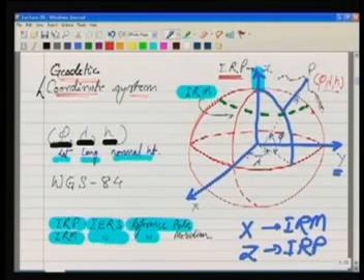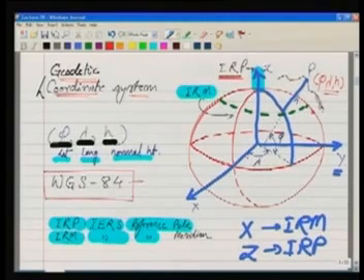So this is the way we represent the geodetic coordinate system. We know our WGS84, which is used by GPS, is also a similar system, and in case of WGS84 we know the parameters of the reference ellipsoid, and the GPS makes use of this. So one system of representing the coordinates is phi, lambda, h.